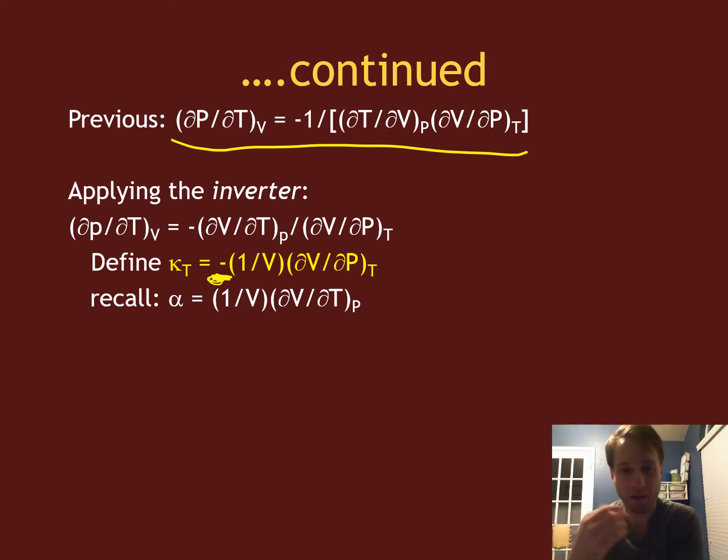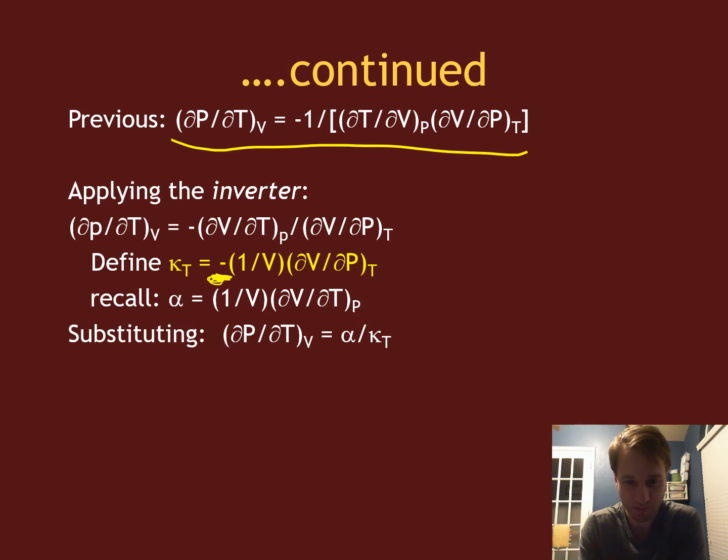And if so, by how much? How much that material is going to compress underneath that weight can make a big difference in the stability of that structure. So isothermal compressibility is a very commonly used quantity in engineering to understand how the volume of a material changes under pressure at constant temperature.